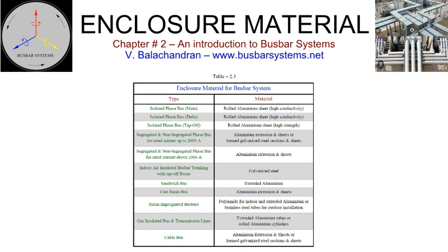Enclosures of isolated phase bus tap-off connections to surge protection voltage transformer cubicle, excitation transformer, and auxiliary transformers run at temperatures that are significantly lower than the specified maximum temperature when operating under rated conductor current. These connections are more often sized to withstand the short time current for the specified duration. The relative size and phase spacing of the tap-off enclosure are small, while it is subjected to the largest magnitude of short-circuit current in a generator connection.